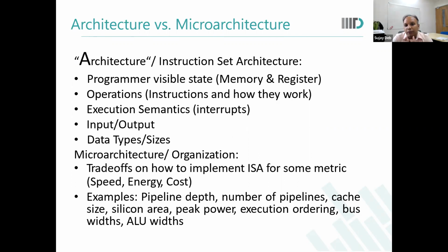If you have a mesh topology, then generally routing is done using techniques like XY routing and so on. Your switch will be routing the packets so that they move in the X direction first and then in the Y direction after the X direction has been covered. These are the kind of thumb rules which are used.